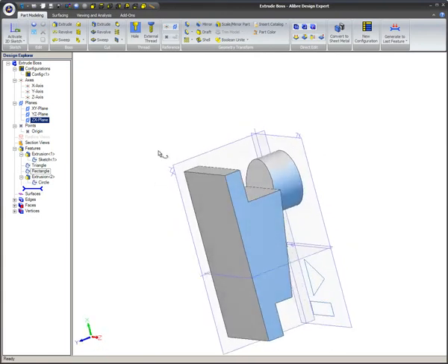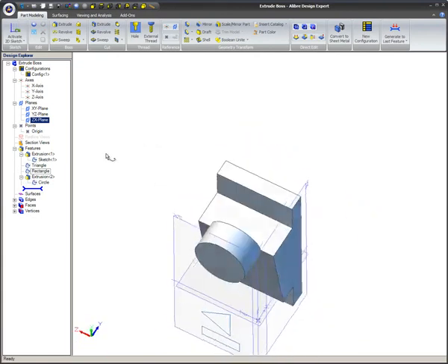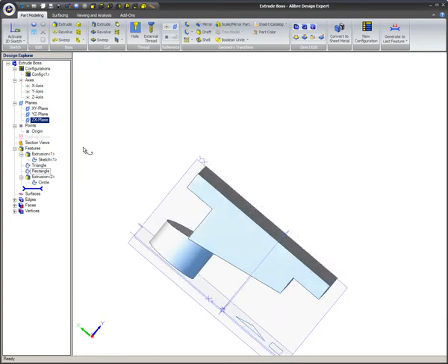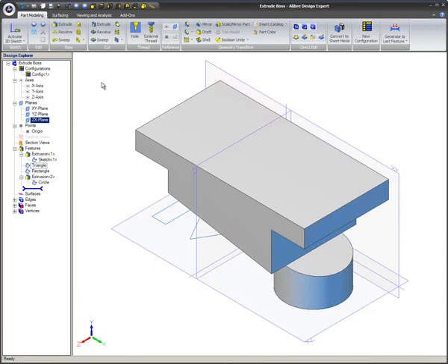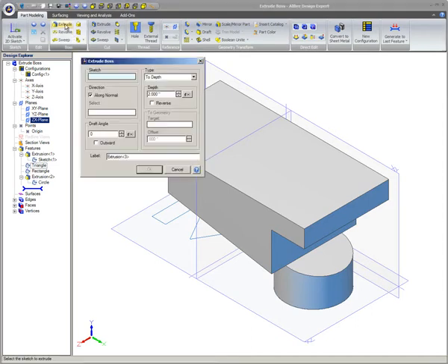When the model is rotated, you can see exactly where the sketch stops during the extrusion process. Notice that the circular extrusion stops at the slanted surface and will not extrude to the next surface. In this example, the triangle sketch is extruded using the To Next option, so you can see the difference between the To Geometry and the To Next extrusion options.